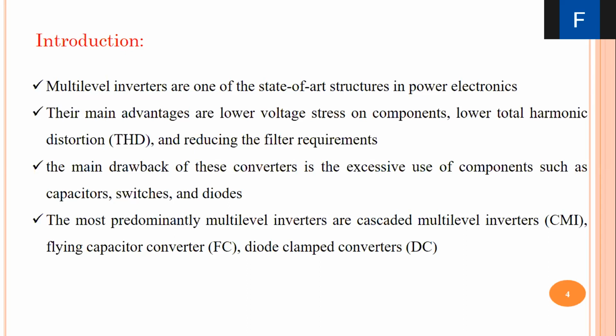In this paper, we use switch capacitor inverters to have more levels in our output, and we try to use fewer power electronic components to generate a large number of output voltage levels.